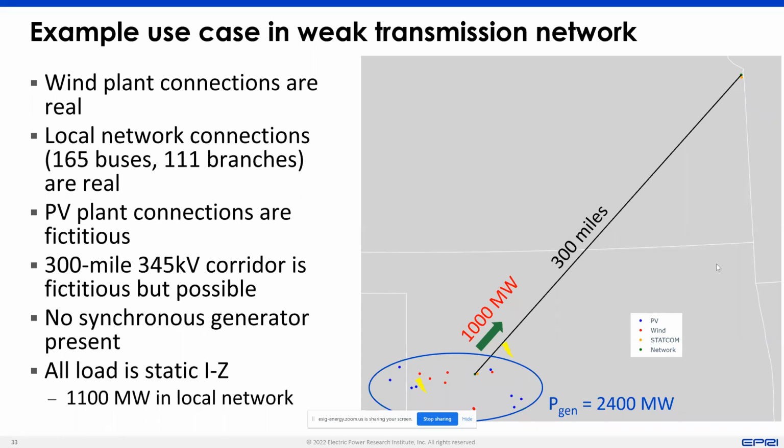Because you have a STATCOM there, can you comment on what that STATCOM does? It does reduce the need to a certain extent, because the STATCOM is providing some amount of voltage control and reactive power capability and providing voltage support there. But it doesn't reduce the need for any frequency response capability from grid forming inverters, because the STATCOM that we have considered here does not have any supercapacitor or anything like that. So it's just doing general voltage control.